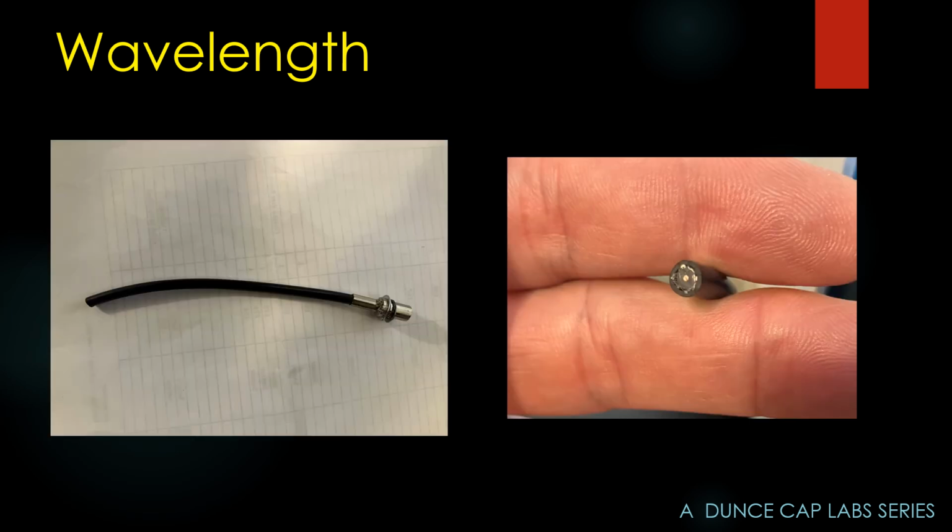I put a connector on, and you'll see the far end, which is on the left here, I'm holding in my hand on the right, and you'll see I've brushed all the copper wire away, insulated the center conductor from the shield. I have an open at that end.